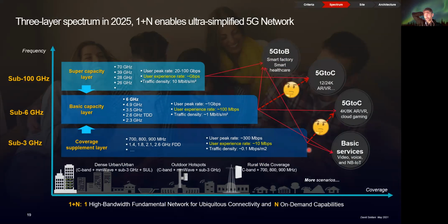So here you have examples of what we can achieve with a high bandwidth, together with the other bands that could be integrated based on demand. If you think of coverage, that can be achieved by radiating in the sub 3 gigahertz, and that allows us to reach rural areas. But as you can see here, as the carrier frequency reduces, the possible transmission bandwidth is also reduced, and accordingly the end user experience deteriorates.